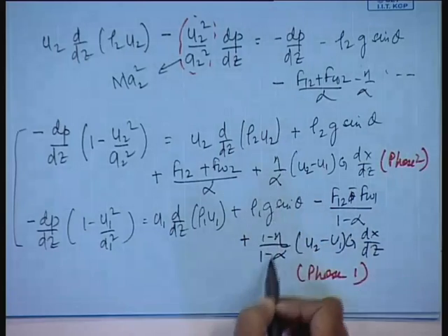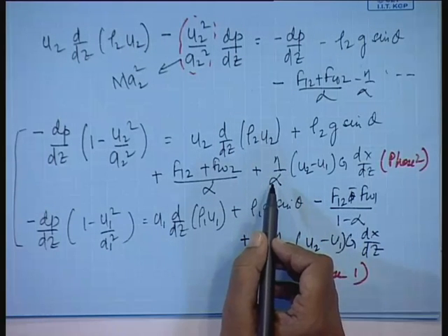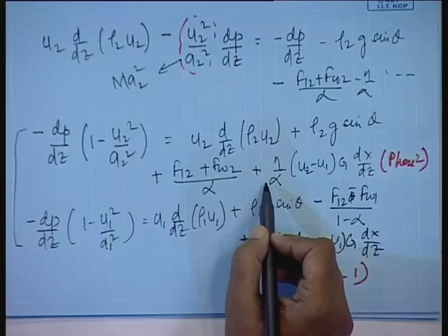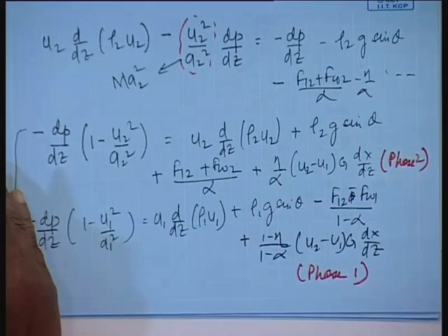Moment there is some alpha part, this alpha is also a function of pressure. So, unless we can account for alpha being a function of pressure and bring those things also on the right hand side, we cannot arrive at the condition of compound choking. Is it clear? So, remember one thing, choking of phase 1 and choking of phase 2 does not give you any idea about choking of the two phase mixture.